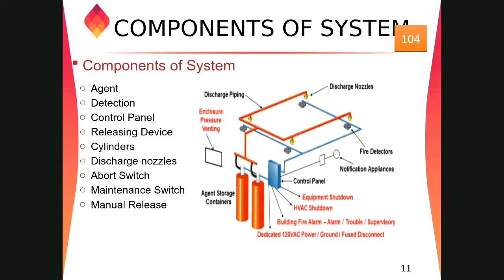So it is a standalone device that will sense the pressure, open and close by itself? Yeah, it is just like a pressure relief system, like a pressure relief valve you can see in our piping. This is a pressure relief venting, which will open at some pressure and then close. Okay, and it will be installed in the structure itself. Yeah, it will be installed within the room and should be allowed for the venting. Otherwise, the peak pressure will damage the system.